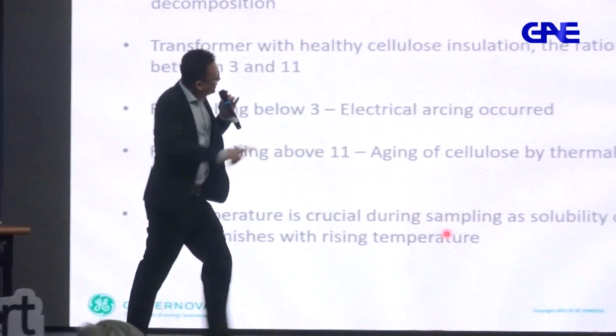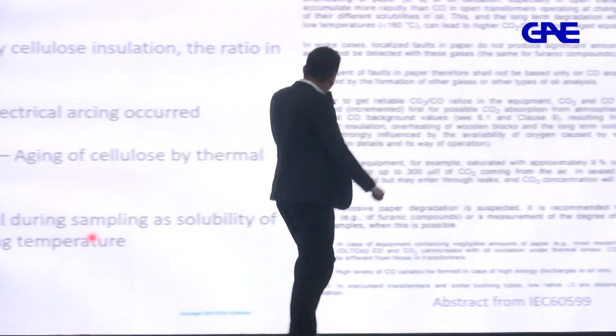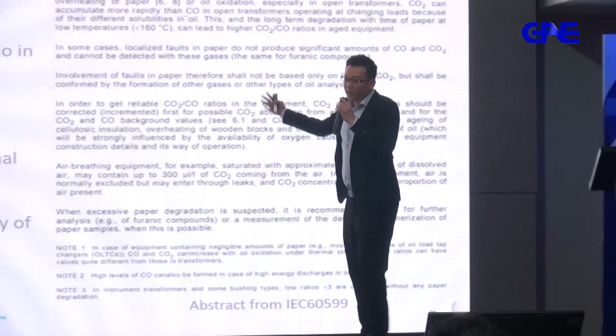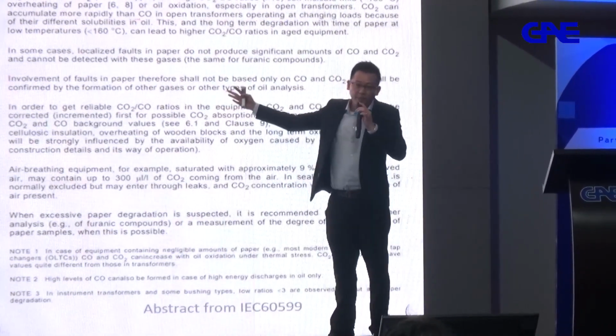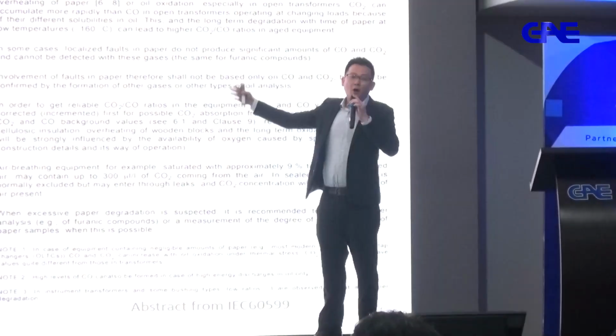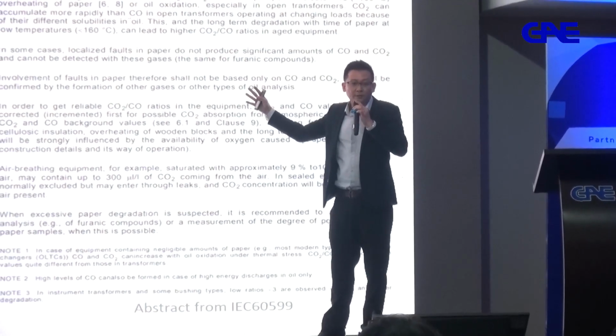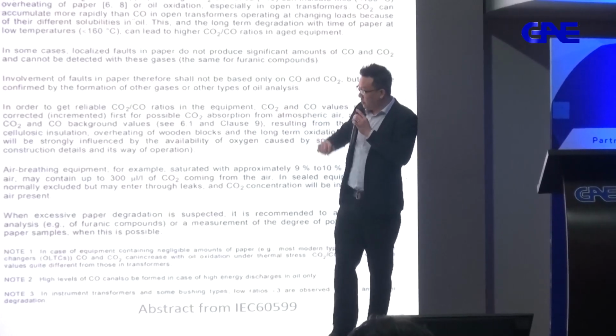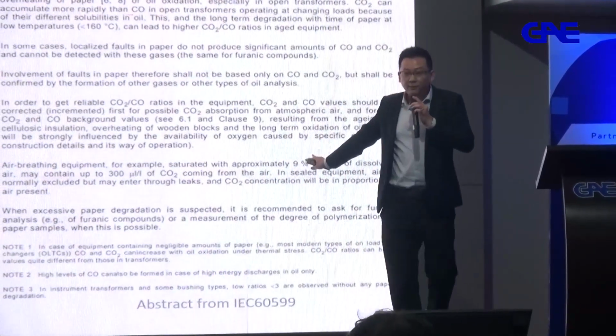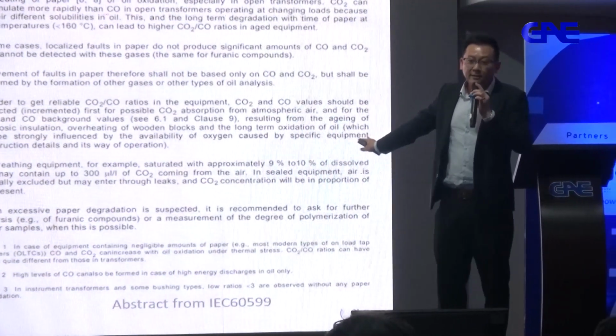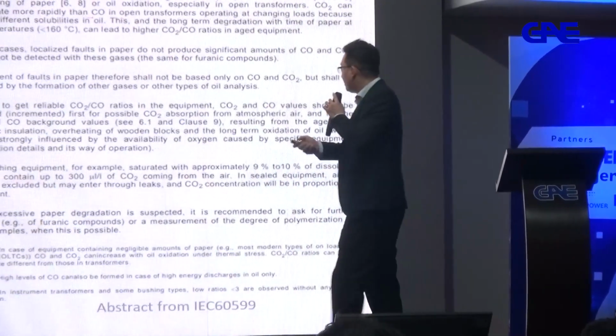So over here, the extract from IEC 60599 is what I've mentioned about, probably 2,500 ppm against 500, or 25,000 ppm against 5,000. So you can take a look. Picture taken, photo taken. Before I go to the next slide, all clear? Let's go.